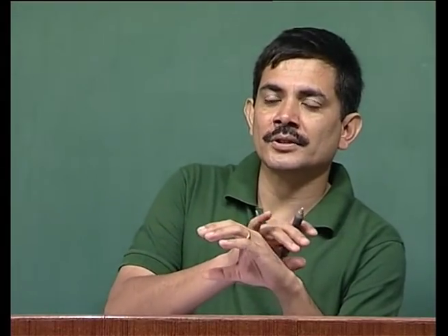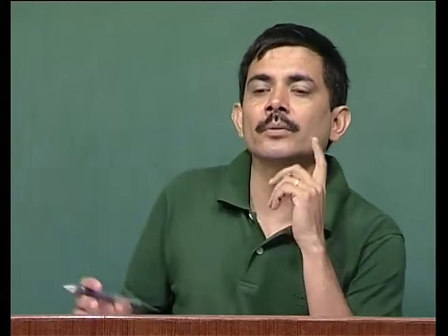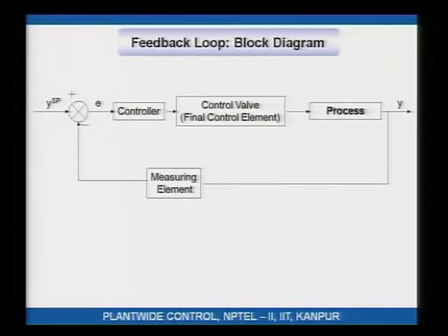We also looked at a feedback control loop: a control algorithm takes in the deviation from the desired value in the output and converts it to an equivalent control action, a change in the input or manipulated variable, so that the deviating variable is brought back to its target value.